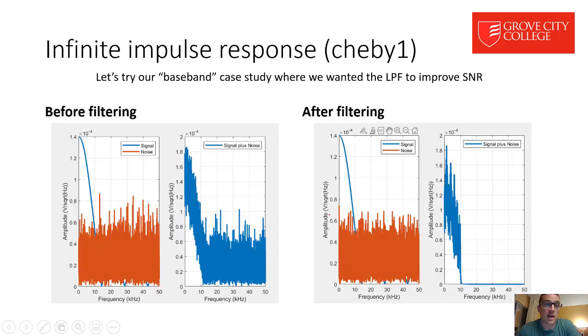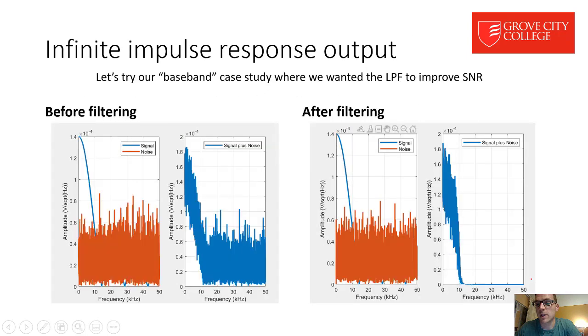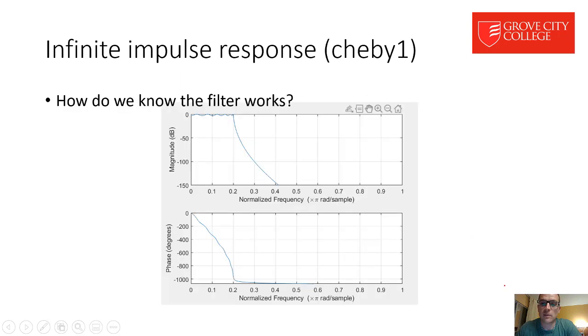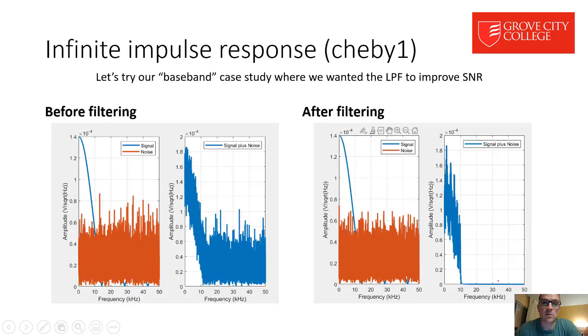So you'll probably have a higher SNR with Chebyshev because you've gotten rid of noise faster, more aggressively, but you may distort your signal more because of that passband ripple. So here's the results from Chebyshev. It cuts off noise really sharply after 10K. Everything just goes to 0 right after 10K. We'll compare and contrast with the Butterworth. See how there's a little bit of transition region with the Butterworth between 10 and 20K. The Chebyshev, it's all just locked off after 10K, just gone.